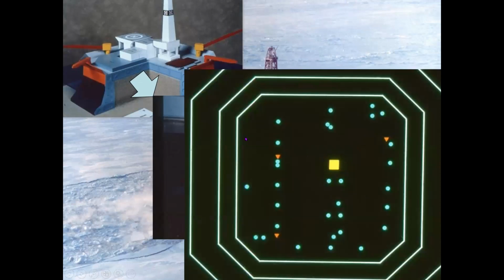This is a plot, and the core of the structure is about 70 meters by 70 meters, give or take. I think it's actually 72 if my memory's not gone. Green dots are CPTs. Red triangles are self-boring pressuremeter profiles, and that yellow square in the middle is the location of the exploration wells we're drilling. And you can see a lot of CPTs. There's actually 33 of them there.